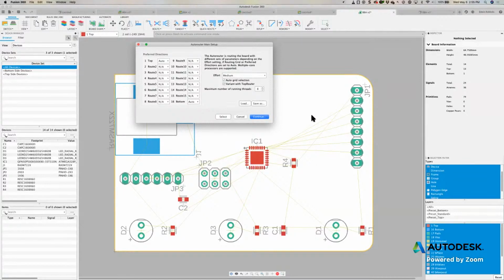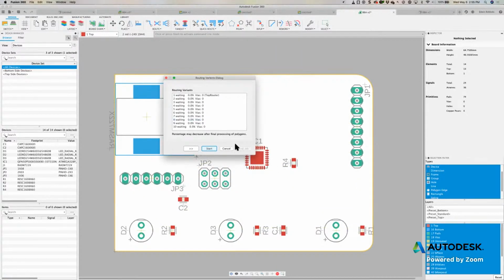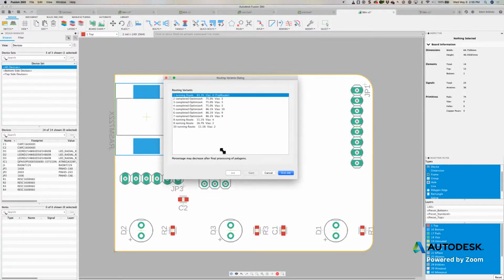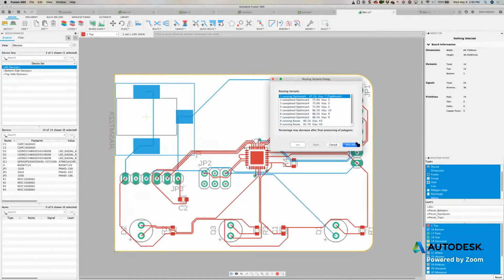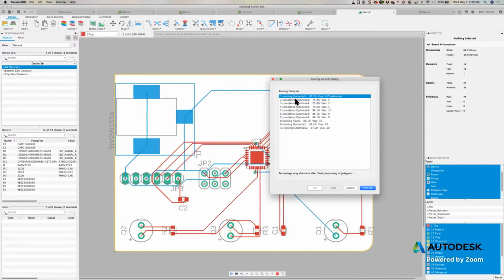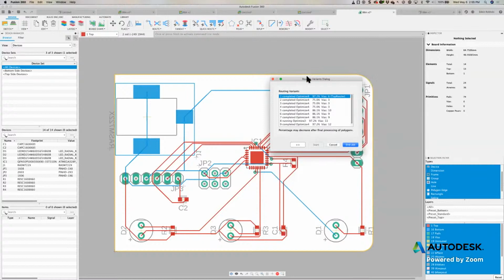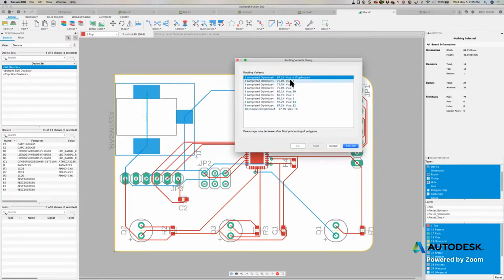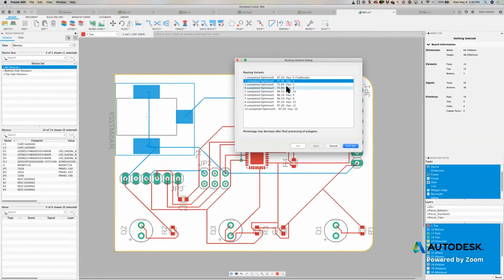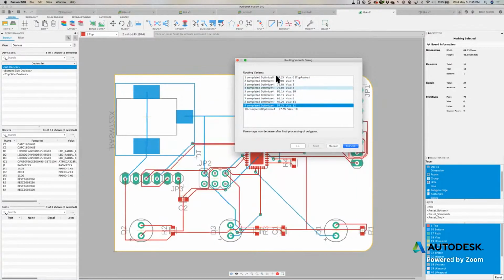Okay, so I'll click on start, and yes, select go ahead and start. Let's see how far we could get. For the effort level here, it actually is going to do 10 runs. As you could see here, it's doing a total of 10 runs. And as they complete, it will just give us a percentage. So the topological router, as well as all the other ones, are actually completed. It was able to do 97% maximum.